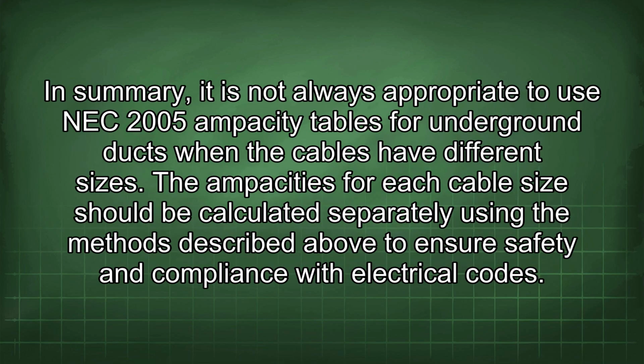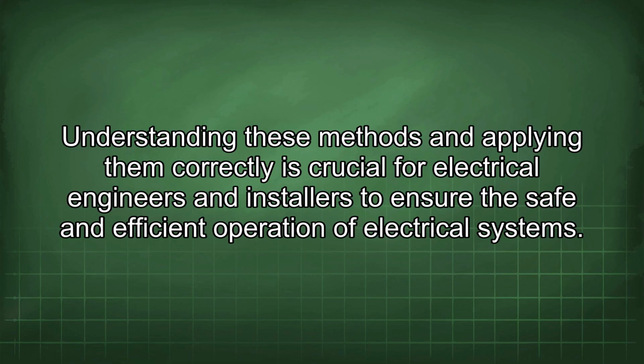In summary, it is not always appropriate to use NEC 2005 ampacity tables for underground ducts when the cables have different sizes. The ampacities for each cable size should be calculated separately using the methods described above to ensure safety and compliance with electrical codes. Understanding these methods and applying them correctly is crucial for electrical engineers and installers to ensure the safe and efficient operation of electrical systems.